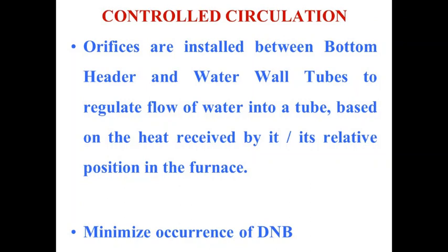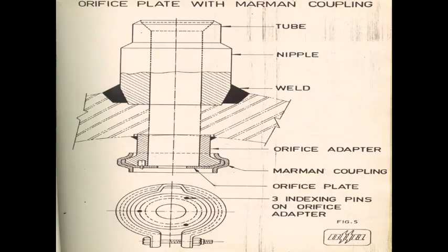Besides that, in the flow passage we have to take care of heating in such a way that crossing the critical heat flux condition never arises, and the flow is entirely within the regime of nucleate boiling, and there is no chance of reaching DNB.